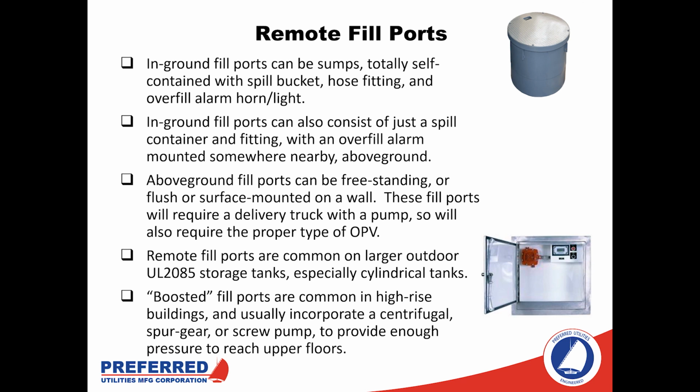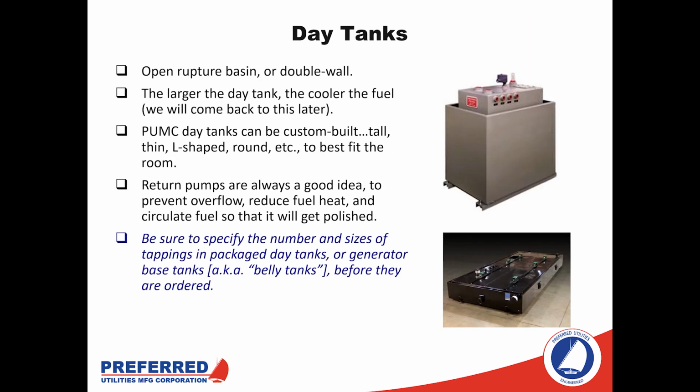The visual alarm, however, will not silence after the 30 seconds or after acknowledgement by the fuel oil fill person. That will stay on. So if somebody shows up 30 minutes later to supply an additional amount of fuel, they'll see a sign and an indication that says if this light is on, the tank is already full or already in high level. The next component we're going to take a closer look at is the day tank.